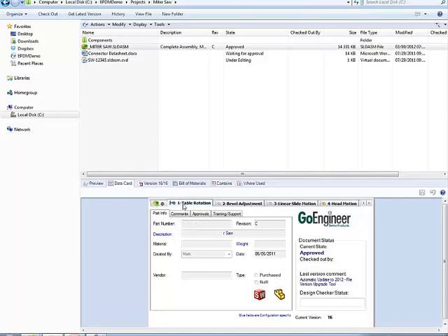And you may notice that there can be different or missing information on the various configuration tabs. The At configuration out here displays the file custom properties, whereas each of these individual configuration tabs show us configuration-specific custom properties inside of SOLIDWORKS.